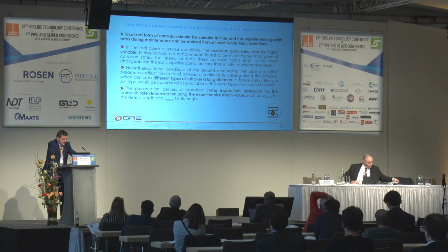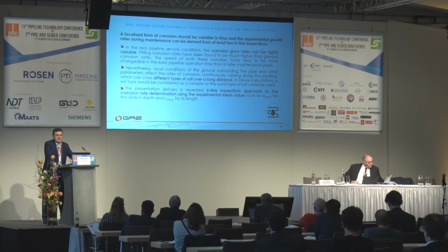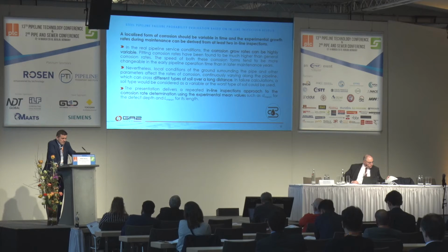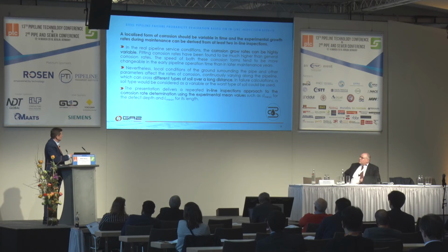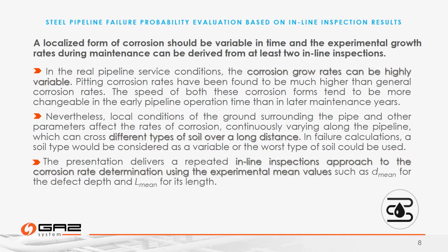In my study, the corrosion rate was determined using two repeated inline inspection data sets. It can be called experimental mean values in this research, derived from two inline inspections.